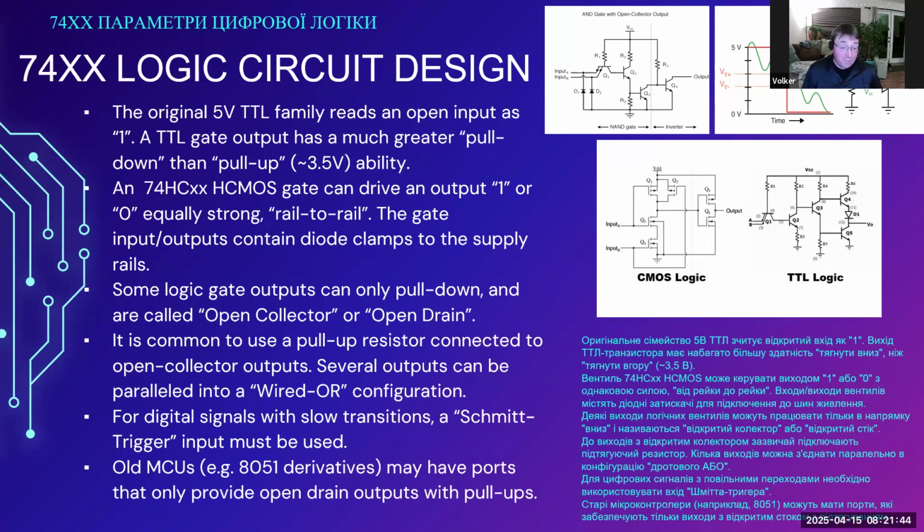You've probably heard of Schmitt trigger inputs if you have worked with digital logic before. So a number of circuits that already exist in the TTL family, NAND gates, inverters, are available with these Schmitt trigger inputs in the same package form, in the same pinout.